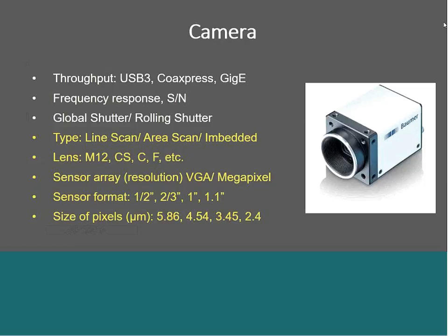So this digital transformation of light into electrical information is an image sensor and the supporting electronics. The image sensor is an array of sensitive elements or pixels, and an individual pixel can vary in size from a micron to several microns, and they're usually square nowadays.